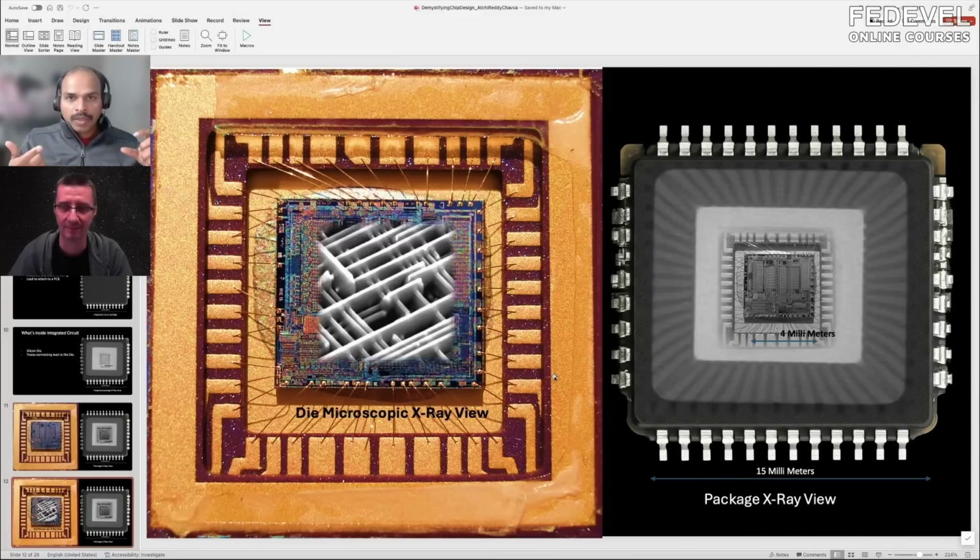To explain that, you start using this, and of course there is wear and tear, just like mechanical parts. Even electronics has wear and tear. The wear and tear, in a sense, is that the device gets damaged because of these charges. It could be some of the wire structures you see here. Pretend this is a water pipe, and you are using it for several years, where we see deposits happening. The higher the deposits, it narrows down the cross section of the tube.